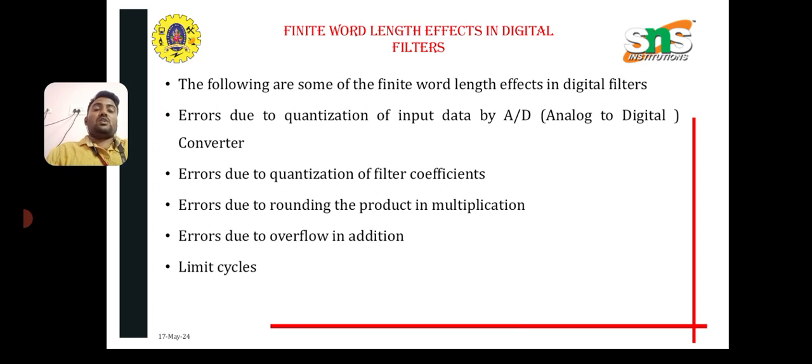Here we have two types of number representations. The first representation is fixed point representation, and the second one is floating point representation. In fixed point number representation, numbers are represented with a fixed number of bits for the integer part and a fixed number of bits in the fractional part. This format is efficient for hardware implementation but can suffer from significant quantization and round-off errors.